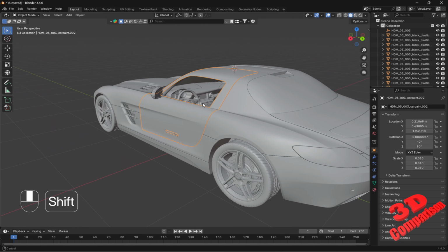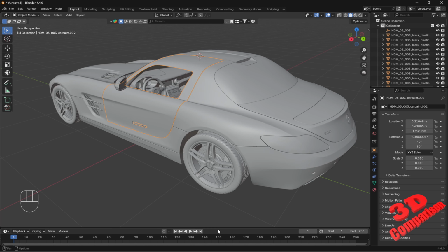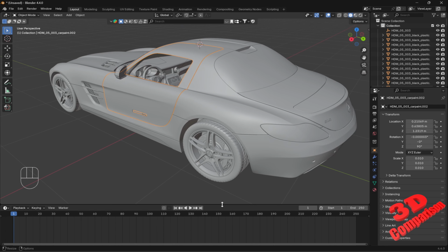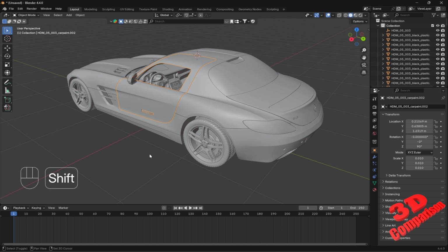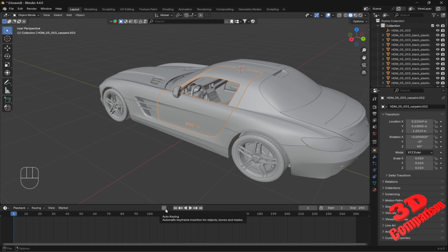We can also define the first animation. So I'm going to further extend over here the animation editor, and I will use Auto Keying in this case, so click on this one. I'm currently on frame 1, so I'm going to keep my mouse within the viewport. I'm going to press R for rotation, and Blender will add a keyframe over there. And let's say that we want this door to open in, let's say, 3 seconds.